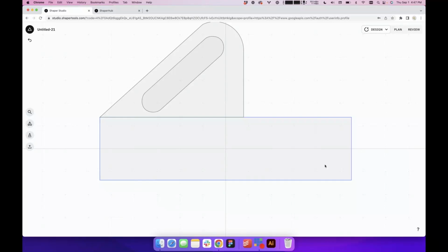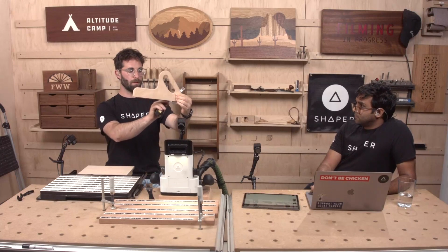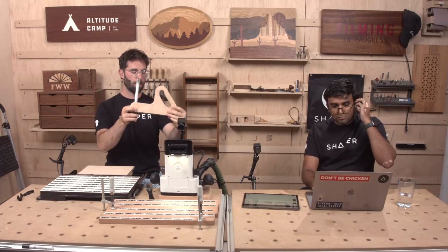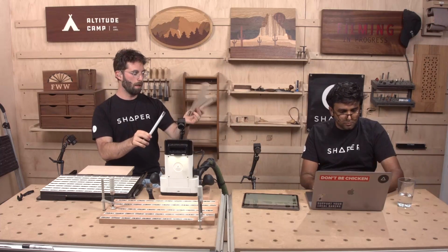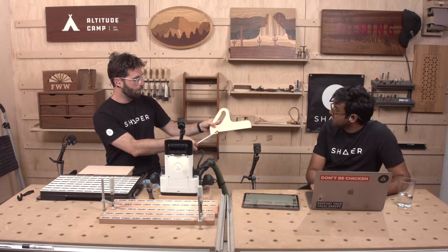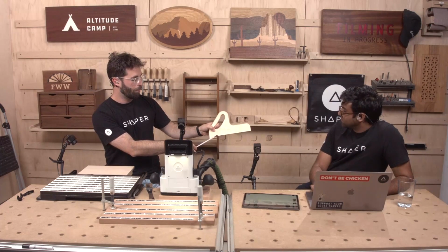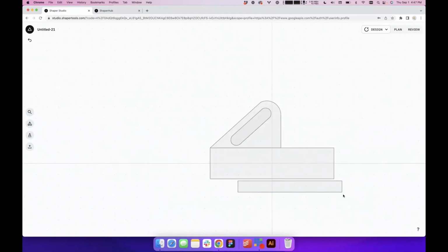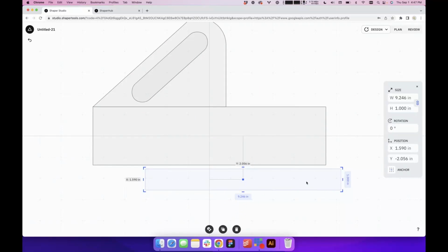We have the shelf that supports the material as you cut it, the actual pushing part. So that's going to be a rectangle that goes along the length, and I want to have a clearance notch here in the back so that I can get a square piece of wood all the way up into that corner. So I don't want a rounded router bit portion there. Perfect. So how much do you want to cut out of that? Maybe we'll call it 1/2 inch. Exactly. And the tail on that is about 2 inches. So that's 11 minus 2, about 9 inches or so.